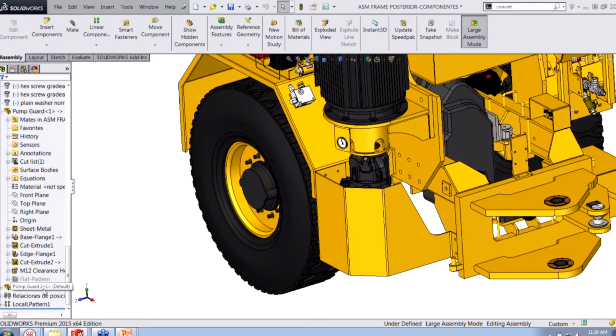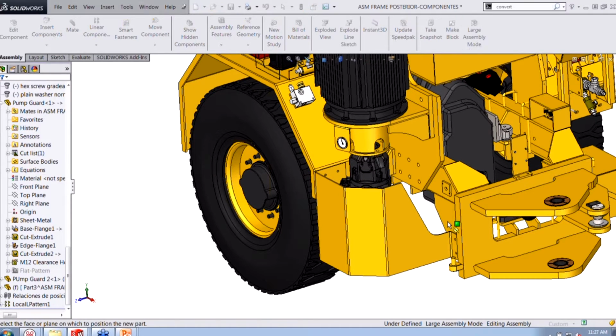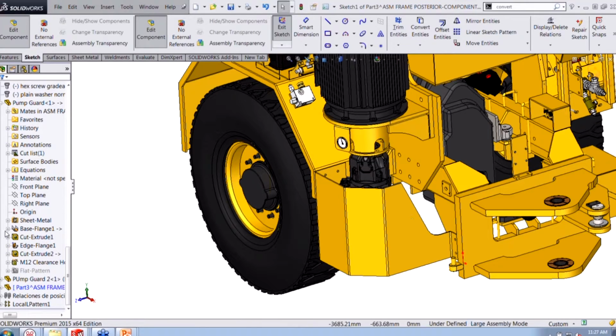So this one here is a real component. It's saved externally already. If I go to New Part, and then just select the face, same one as I did before, you'll notice on the left-hand side, it says brackets, and there's also a caret up to show you which assembly it's a part of. Okay, the biggest giveaway would be the brackets. Besides that, there's really no different icon or anything like that.